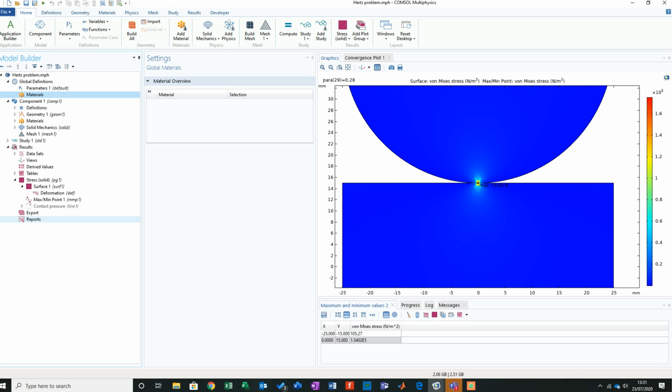The thing with SolidWorks is that it is restricted purely to tetrahedral mesh, which is not a problem, but it can limit you if you want to do a lot more in-depth simulations. The beauty with COMSOL is you can build meshes yourself. You can say, this type of mesh, I want it to be like this, and to continue along a flow. So you almost model the mesh. With ANSYS, there is an adaptive process, which you can then build on top of. So it just becomes your real weapon of choice.